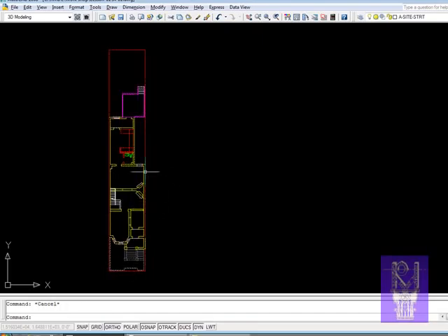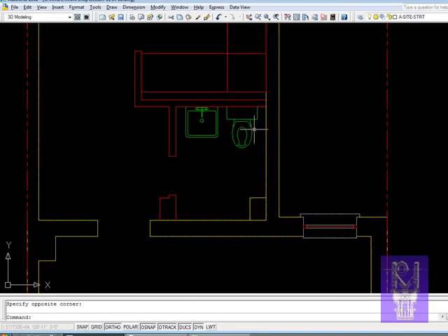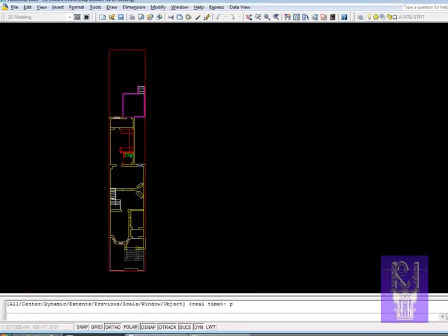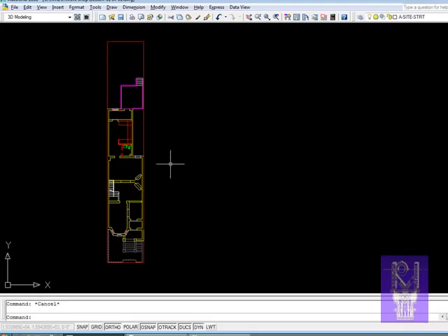Okay, so now the next thing we wanted to do is move the toilet and sink from this wall over to this wall. We want to mirror this whole condition. But before I get too far ahead of myself, let's array this whole system first, and then I'll change that condition in the bathroom, and you'll see it'll change everywhere else. This is a very efficient way of approaching this condition, or most conditions in AutoCAD.